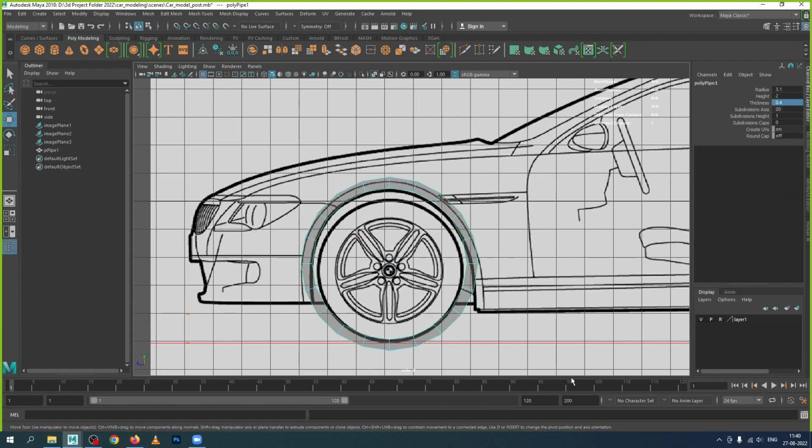Now what I am doing, right click on this one and go to the faces mode. Why faces mode? I don't want this bottom. Why? Because it is not a body, it is an open area. So select this marquee selection from the bottom here, now till here. Because my body is coming till here, so I need this bottom portion also. Here also this bottom portion, if I need, I can keep, otherwise I don't need this one. So I'll delete this portion from the bottom now.